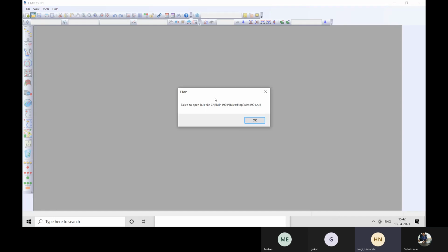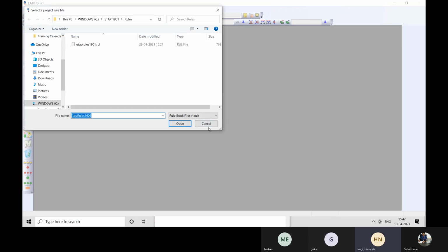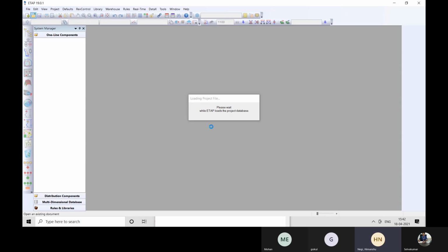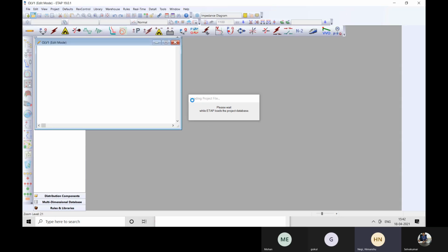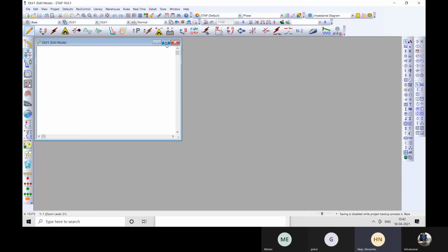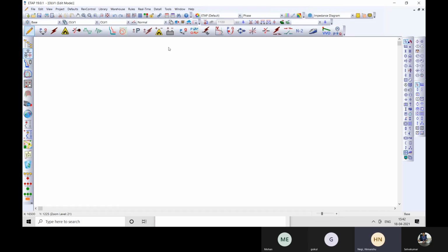So if my MAT value is say 2 ohm, 5 ohm, 10 ohm of substation resistance, as long as that substation is connected to the various overhead lines, then we don't treat that impedance or resistance as high, because it is going to decrease because of various parallel paths of overhead line tower footing, and we call that an overhead line chain impedance.